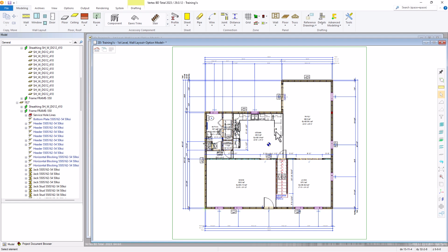After completing all the wall framing edits, the next step is to create the panel drawings. Create the panel drawings for individual walls or for all the walls in one step. It's important to note, if panel drawings already exist and you select Create Panel Drawings, a window prompting the user to either replace or update the existing panels will appear. Replacing the panel drawings will delete the existing panel drawings and prompt the user to select a new wall panel template. Updating the panel drawing will keep the existing drawings, but update the material schedules and the existing drawing and elevations on the panel drawing.